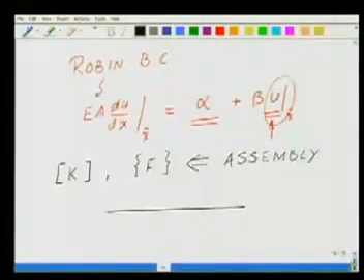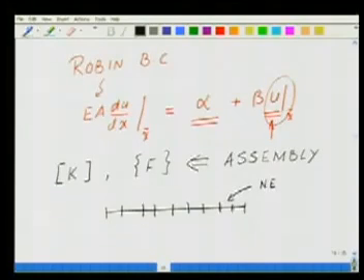And you see, the beauty of it is that out of our element calculations, the stiffness matrix and load vector came out automatically. Now the question is, if I want to change the number of elements in the mesh, no problem. If I want to change from 6 to, let's say, NEL elements, these could be non-uniform.